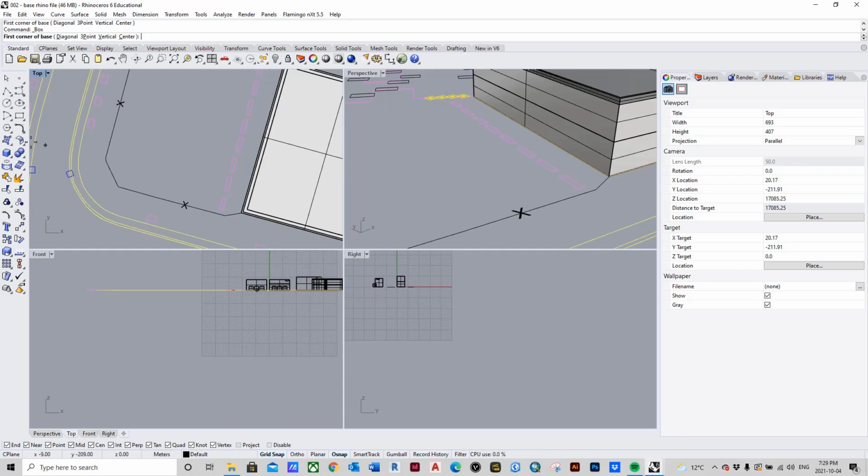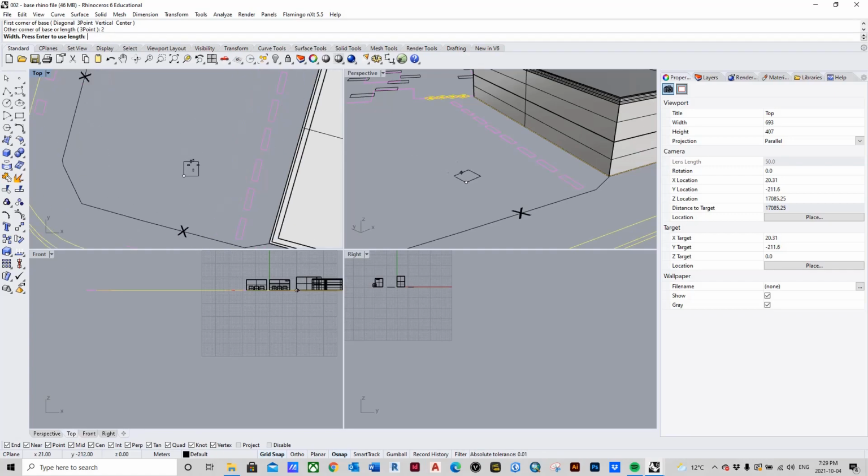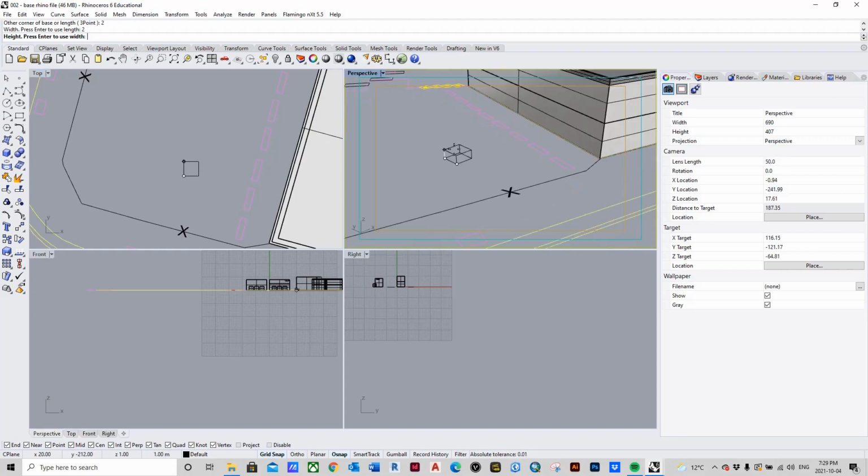With the box selected, we can click anywhere in the top, and then first we're going to type 2 for 2 meters and hit enter. As we can see right off the bat, in the left-right direction, it automatically has it stuck on 2. That 2 is set. So now when we type 2 again, enter. Now look, we've got a 2 by 2 face that we're working with.